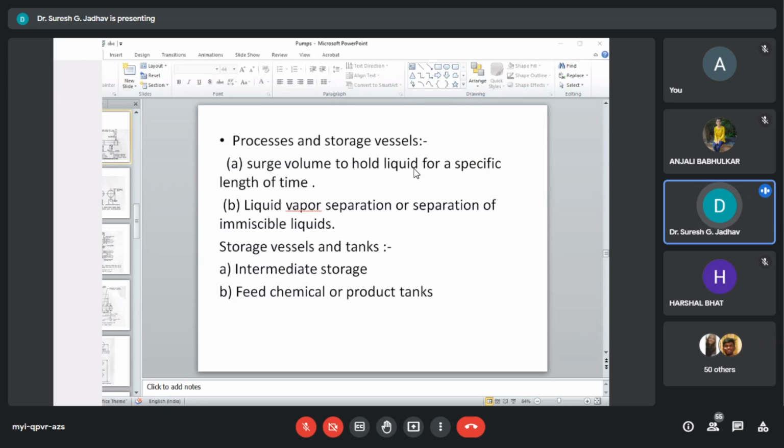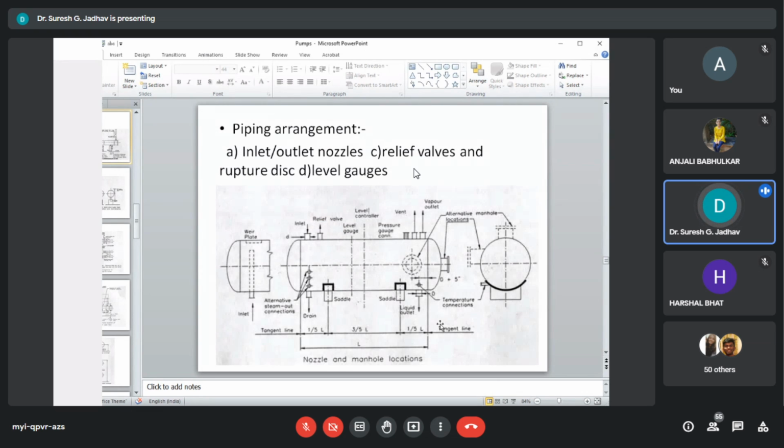These tanks are conical roof atmosphere storage tanks to store bulk chemicals. If the storage demands high pressure, these are designed as horizontal bullets or spheres. The relevant statutory requirements govern the layout of these storage tanks, and these specs are already covered in the development of plot plans.